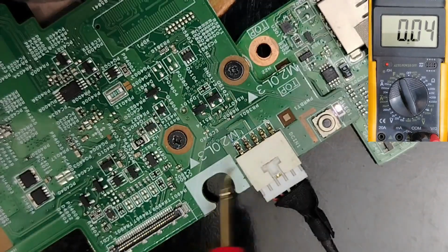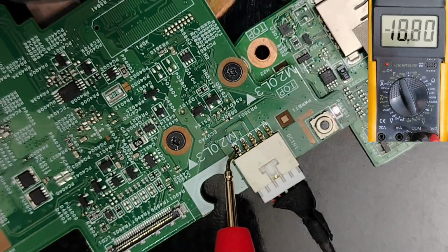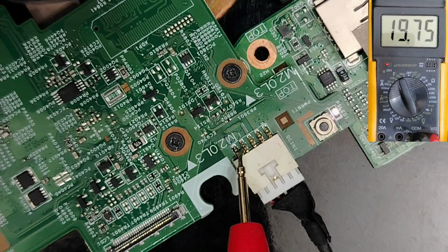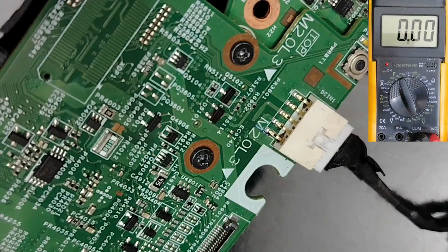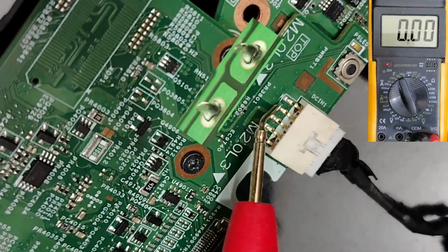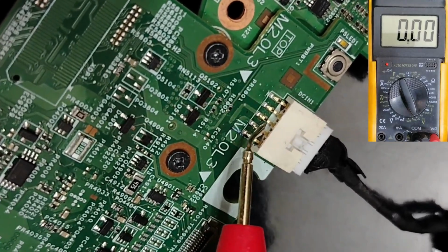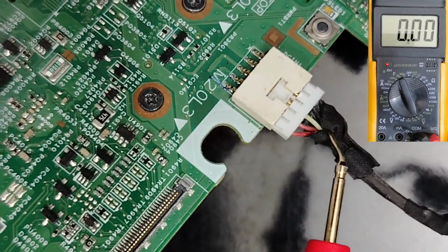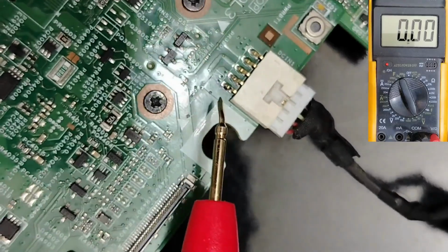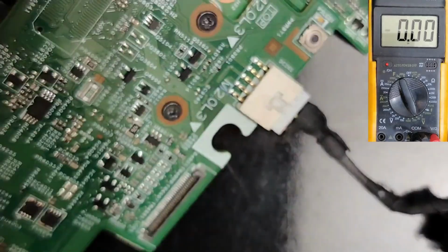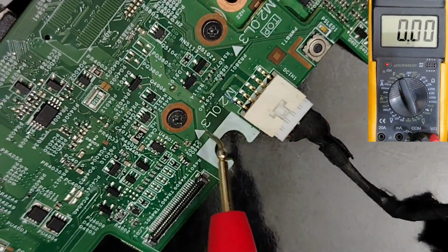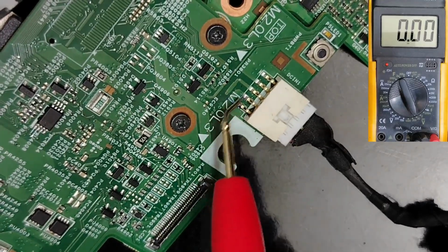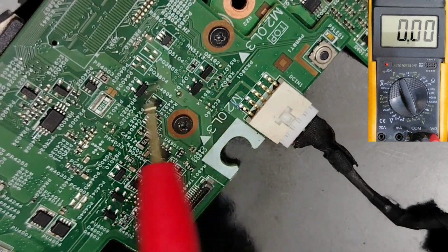Of course, for some motherboards, as you can see, if you check here, for example, for this motherboard we have 19 volt. This is good. In this pin also we have 19 volts, so this is basically a good motherboard, okay? But if there is a dry joint, guys, even if you find 19 volt in these two pins, because here basically we have red wires, which means these two pins hold 19 volt. This is the problem that some technicians make: you check here, you find, for example, 19 volt, but if there is a dry joint, the 19 volt will not pass to the motherboard.